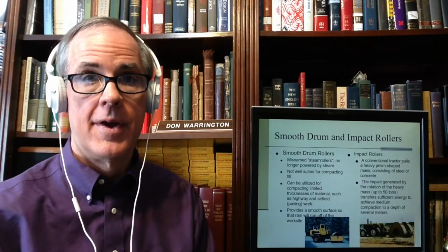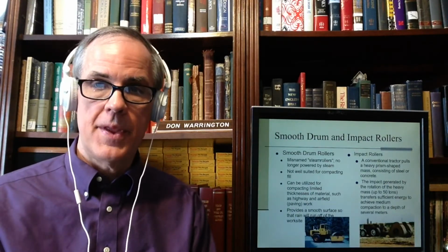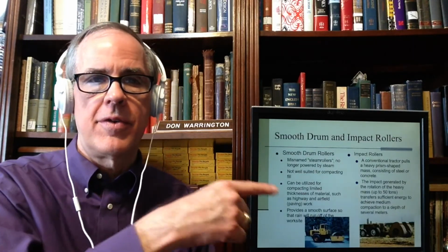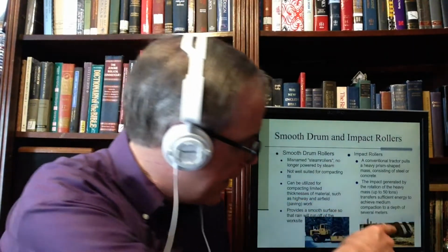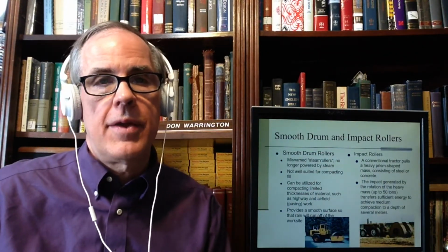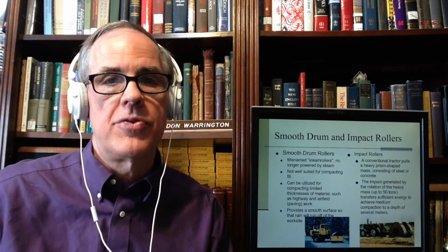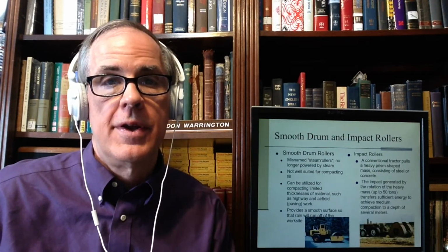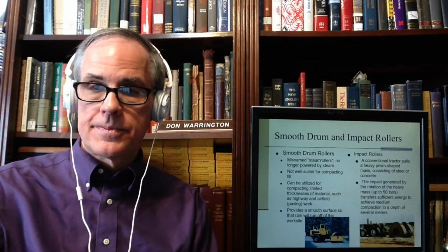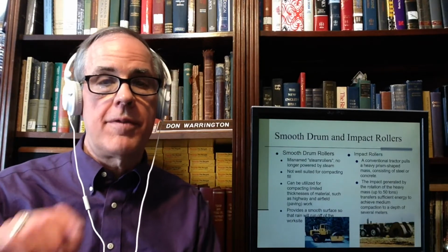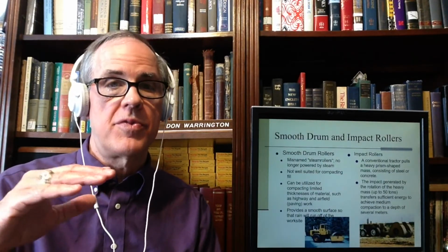We also have impact rollers, those big triangular things you see over there. They actually make impact, and we'll see another method of impact compaction here shortly. The thing about impact compaction is that it can compact soils to a very significant depth.